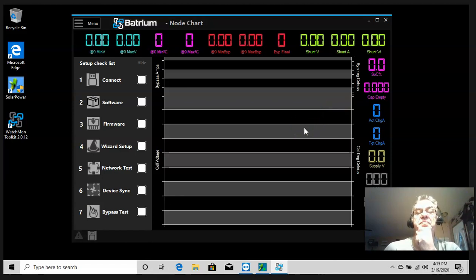And I've got some pictures I've posted, and I'll probably make some more videos of how I do that as I create these batteries. But it's going to be the 18650 cells in bricks of 150, so that'll be 4.1 or 4.2, which I probably won't run them that high. Once I start using this, it will be probably 4 volts, and I'll run them down to probably 3 volts at the lowest.